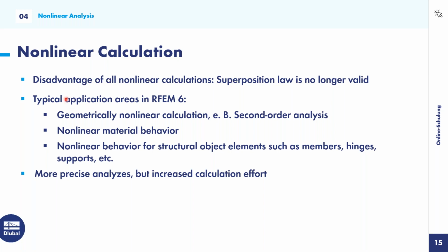So, what are typical application areas in RFEM 6? We have, as I already mentioned, geometrical nonlinear calculation, like the second order analysis. Additionally, we have also the third order analysis when I consider any tensile or membrane structures. I have also nonlinear material behavior, which is also very interesting because I have prepared an example for you.